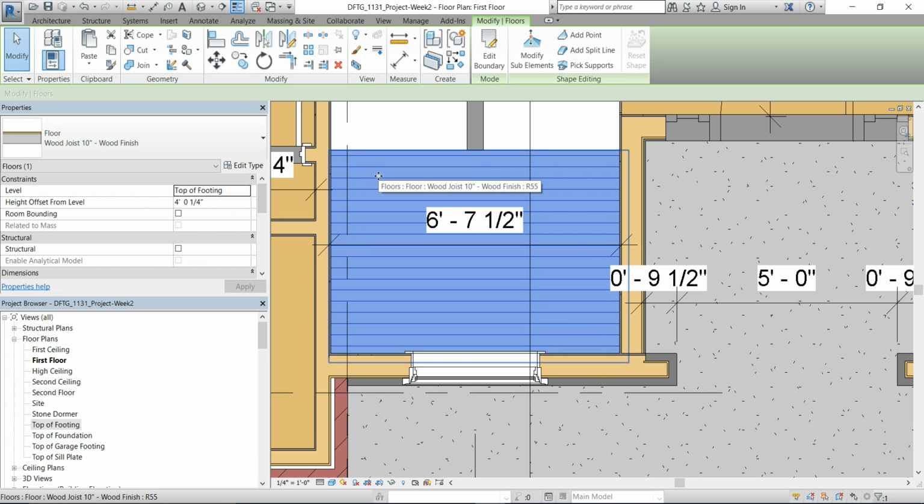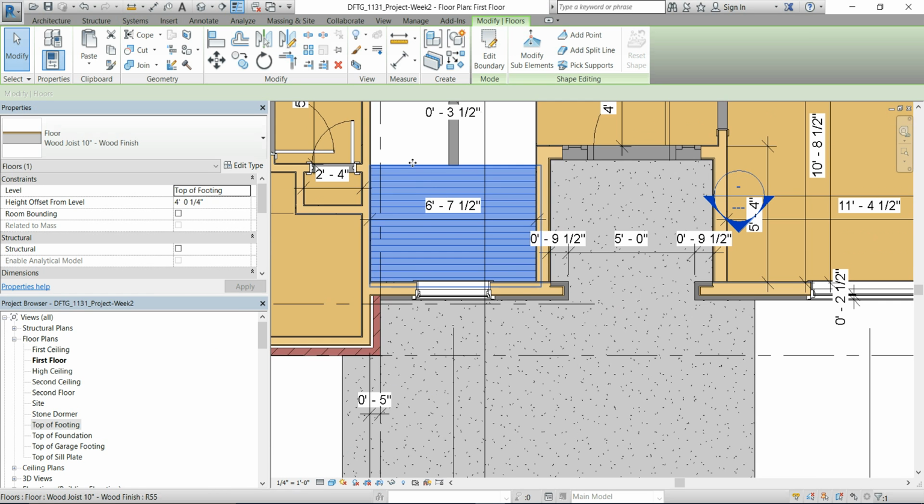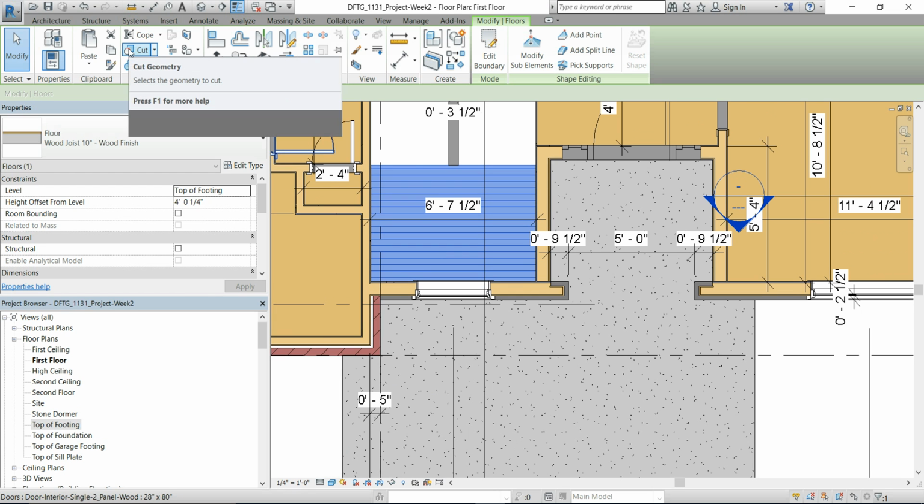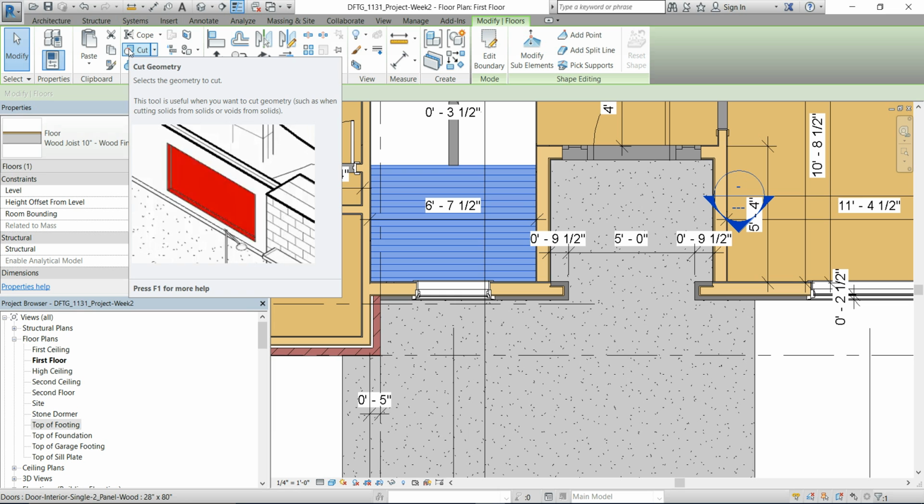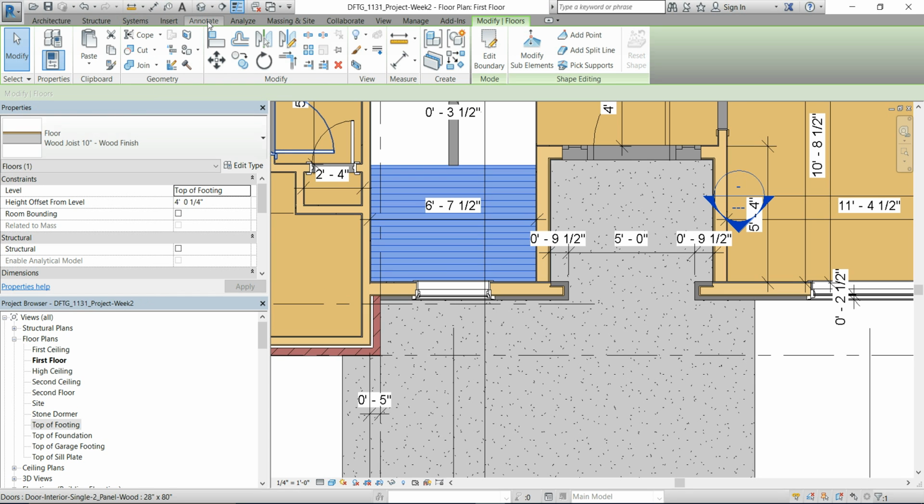All right, so I put that in and cut it in. When I did the sketch, it extends into the core boundary, so it goes to the studs and to the concrete on either end. You just have to look at your plans to see the height of those. On sheet number 3, first floor plan, it gives you the height of those, but those dimensions are to the plywood subfloor.